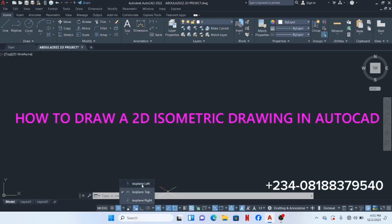So now I have the isoplane left, isoplane top, and the isoplane right. The isoplane left helps to align snap and grid along the 90 and 150-degree axis.